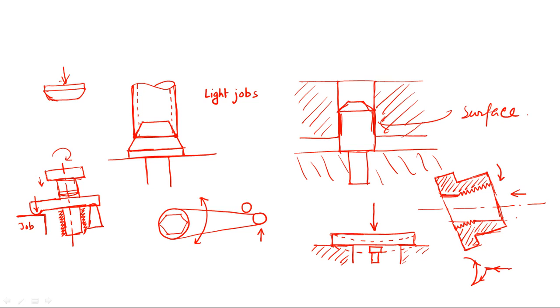So at first we will press the nut, then we will apply the force so that these threads will get engaged with the thread of the shaft or the job, and then we will rotate it in the counterclockwise direction. Okay, so with the help of this quick acting nut, we can quickly hold the job so that we can perform the job quickly, and within a short period of time we can produce more products.